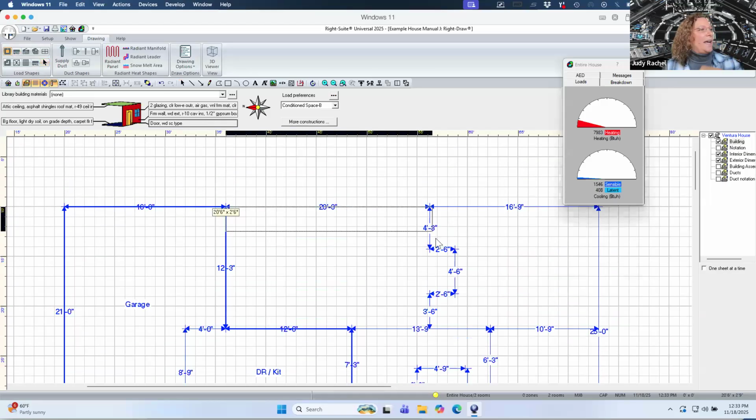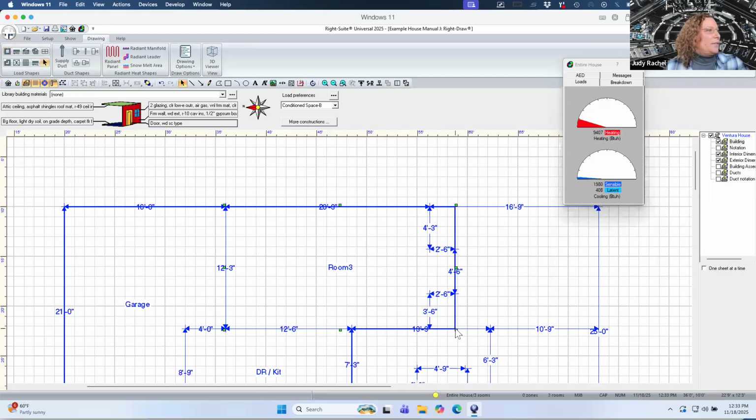And the living room actually has a fireplace. And so you're going to notice that we're giving the fireplace to the living room. And there's choices that we need to make as to some certain spaces, what room the load actually belongs to. So the fireplace opens into only the living room. It doesn't open into the bedroom that's on the other side of it.